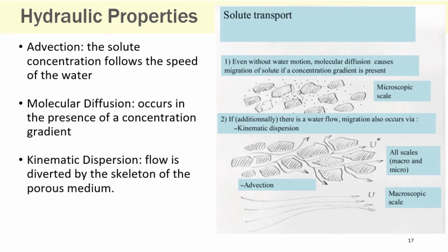Water is nature's way of transporting radionuclides away from deep repositories, making hydrology quite relevant. It can be studied by two methods, looking at the movement of the water and looking at the movement of the solutes. The three main factors that influence solute transportation are described by advection, diffusion, and dispersion. There are other influencing factors outside these three, such as chemical interactions, but these are the big three.